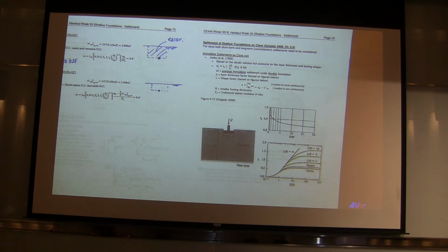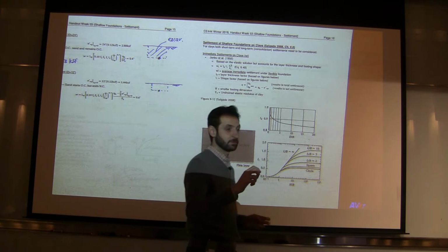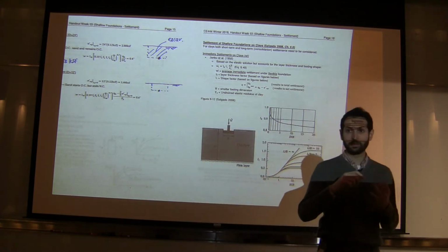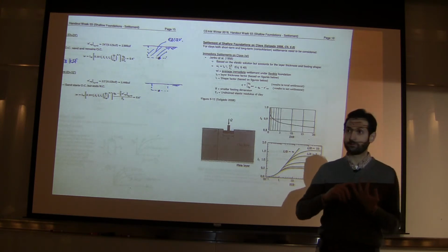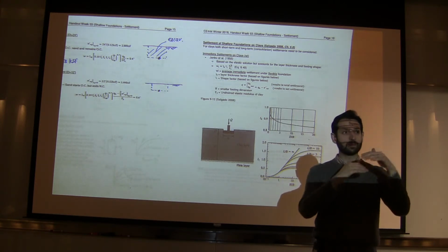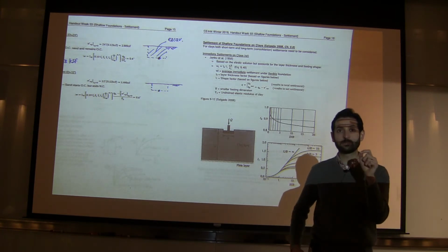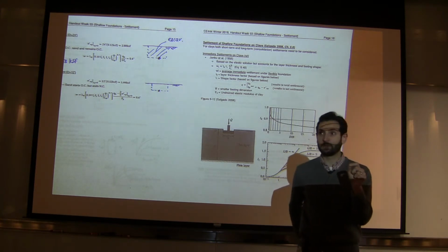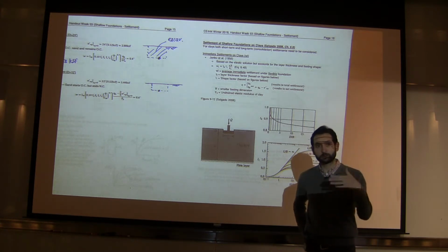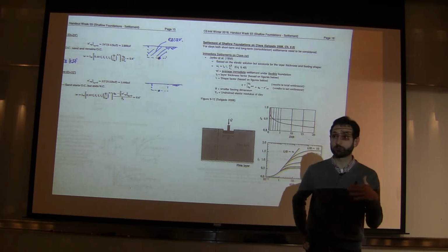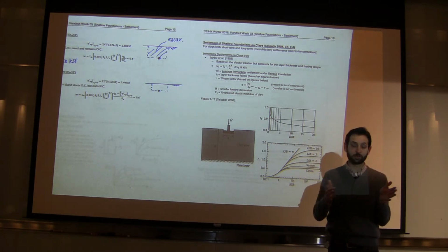of consolidation. And I want you to check this when you're doing your homework 3 assignment, because in homework 3 you have a settlement calculation in sand, and then you have another problem, a settlement calculation for clay. And for clay you have to break it up into the immediate settlement and the consolidation settlement. After you're done, I want you to compare the amount of settlement that you get from the immediate settlement to the consolidation settlement, and see for yourself if that consolidation settlement is large or not. And I would tell you that the consolidation settlement should be pretty large.